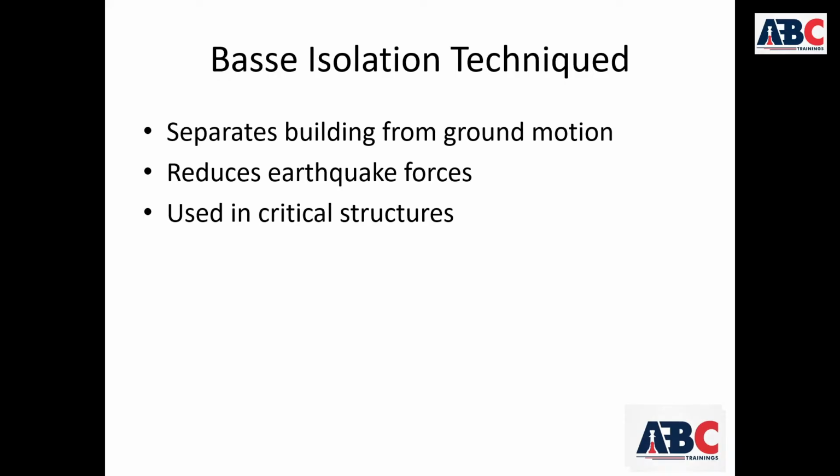But in base isolated buildings, special devices are placed between the foundation and the superstructure. These devices absorb and reduce the energy. Base isolation works by increasing the time period of the building.